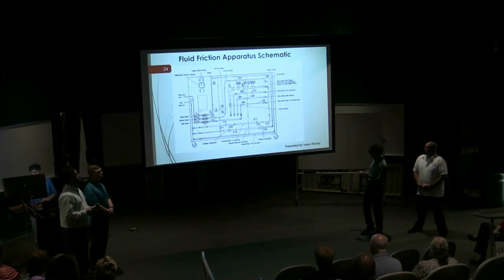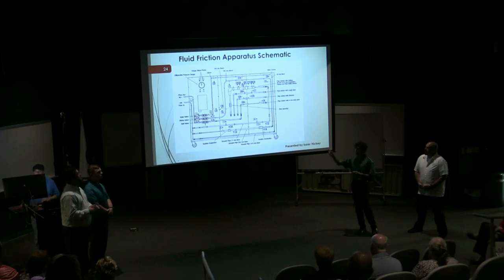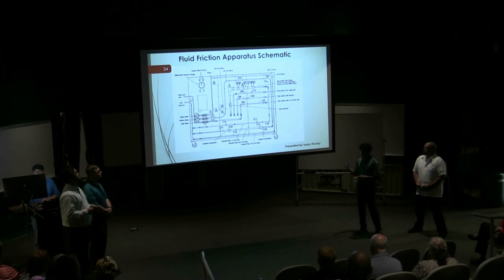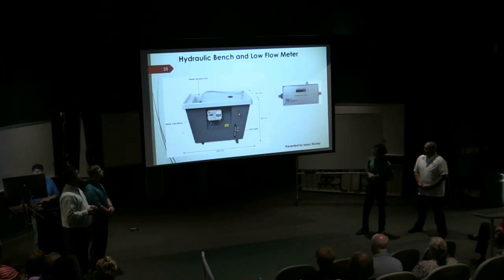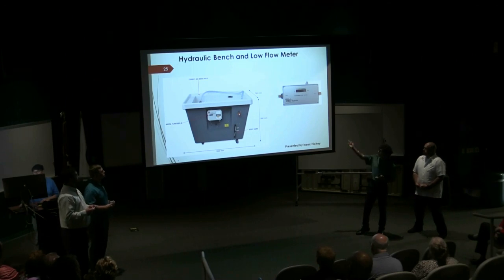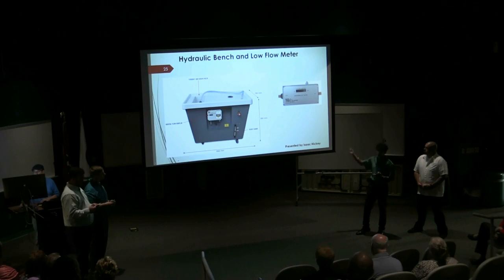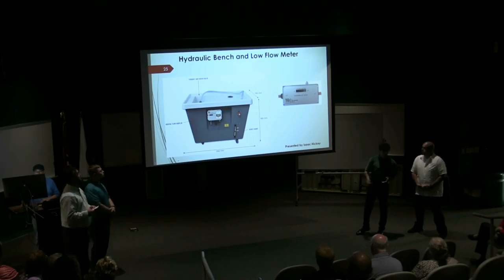This is the schematic, which shows where all the pressure taps are and everything's numbered, so you know where to plug everything in to make sure you're testing the right stuff in the system. It's from the manufacturers, and it helped us a lot during this experiment. And this is the hydraulic bench, and it also has the low flow meter to see how much water is pumping into our system in gallons per minute.